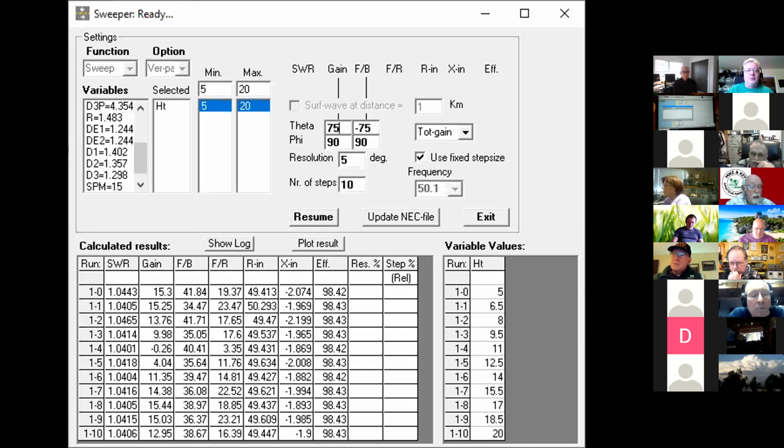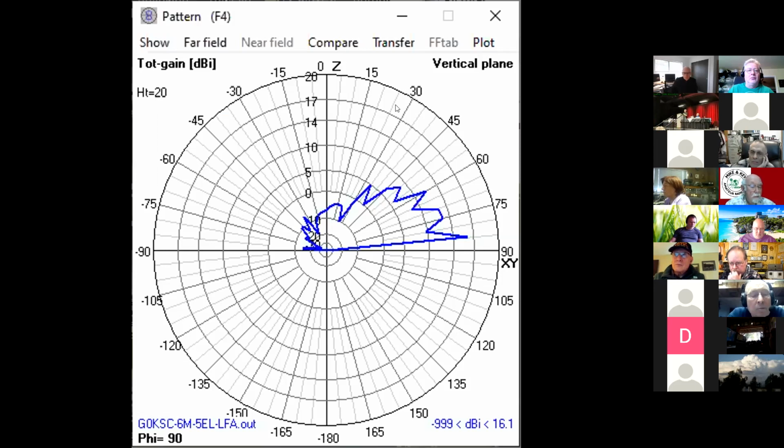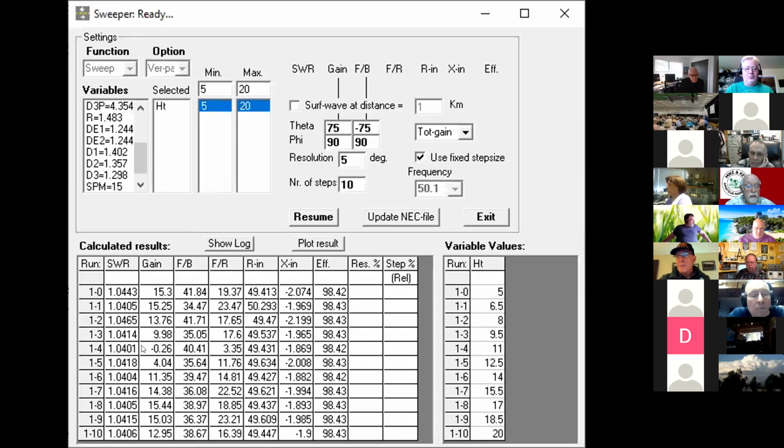Now, we could sweep this in degrees. As soon as you find out where these guys are, the actual pattern nodes, let me show you what I'm pointing at. All right, these pattern nodes are at a certain degree. We're looking at 75. So clearly the pattern shifted to move higher or lower than the 75-degree theta. Okay, and that's why over here it shows this minus 0.26 dB.